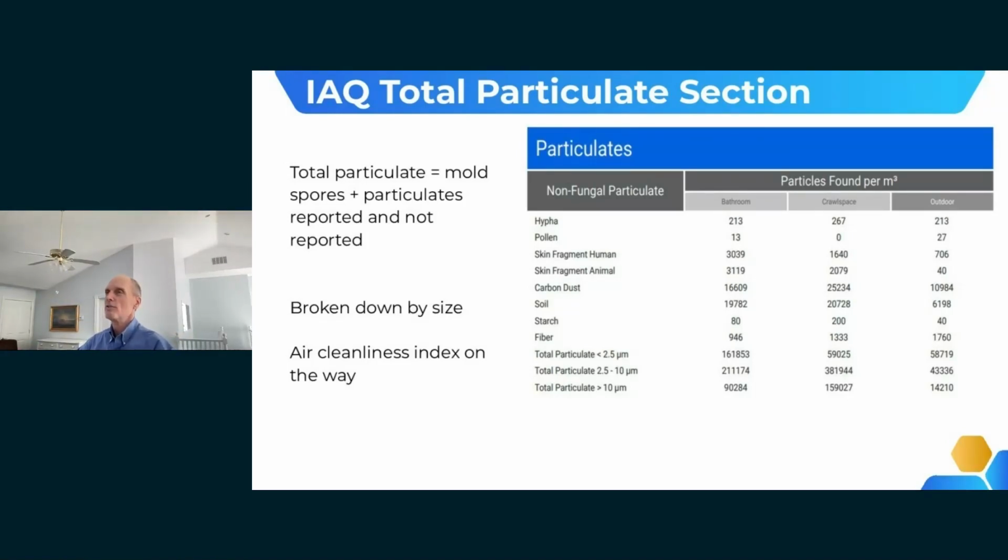And that might be a good thing to mention right here: when you do an air sample, 5 minutes at 15 liters per minute, that covers roughly an 800 square foot area. So if you're in a big house, one air sample isn't going to capture everything in that whole big house. And also if you've got hallways with doors, you can't always say, hey, we're getting everything.